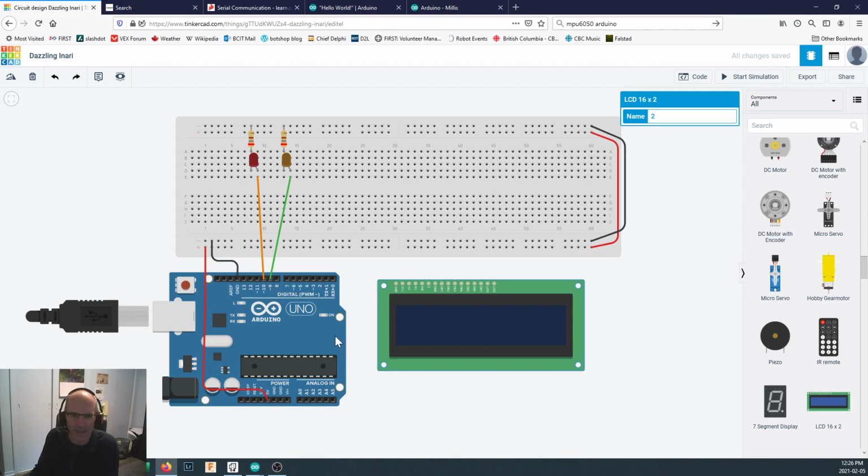Now, over here on this side of our Arduino, we've still got it hooked up. So we've got a line going in here, and this header all along here, and this header all the way up here are all connected to the black wires that go into the GND port of the Arduino. And anytime you have two devices trying to communicate to each other, it's really important that they have a common ground. Here we've got 5 volts coming along right here, and that powers this line right here. It comes along and powers this line up here too. So we're going to have a source of 5-volt power, and that's going to come in on our VCC line right up here. Okay, VCC is often used to indicate the power.